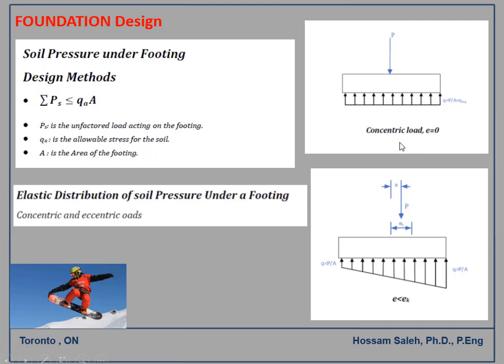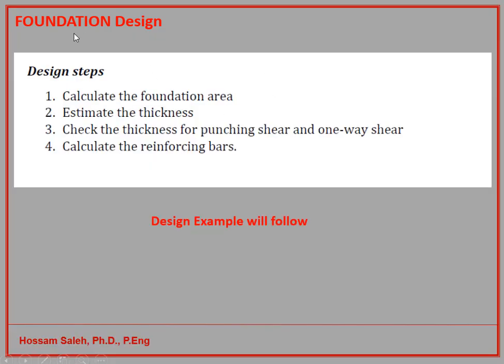And this is a big item to look at when you are looking at the foundation wall, because the foundation wall will be at the property line, and you want to make sure what the edges for the foundation are. So the architect should consider that when they put the footprint of the building, and the structural engineer should coordinate together with the landlord about whether they are allowed to extend the foundation to the outside of the property line or not.